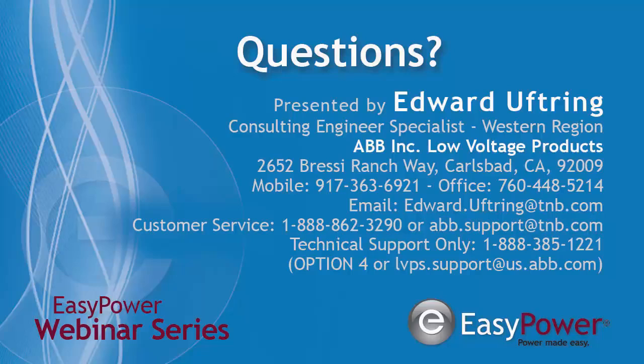I see it as a problem when you have different manufacturers, since breaker curves depend on each manufacturer, we require them from the manufacturer with submittals. Do you see any problem with that? At ABB, I can only speak for us. We're very quick with that submittal. We have most of our trip curves up online, so you can download them. We do work with EasyPower, and we're working with them to make sure that when you do have an ABB product, the trip curve can be found on the website or a link, so that you just have to click on it to find the trip curve for that.